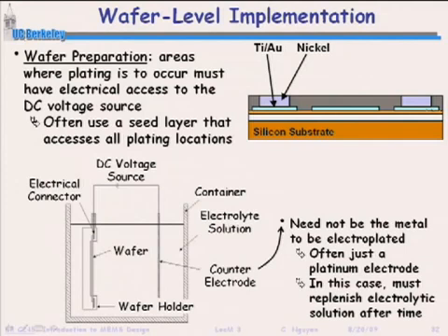And then at this point, you have to dip the whole thing in an etchant that attacks nickel. That's going to attack some of the structure too. But if the structure is much thicker than this seed layer, you'll just get rid of that seed layer. Then you attack the aluminum and aluminum only.